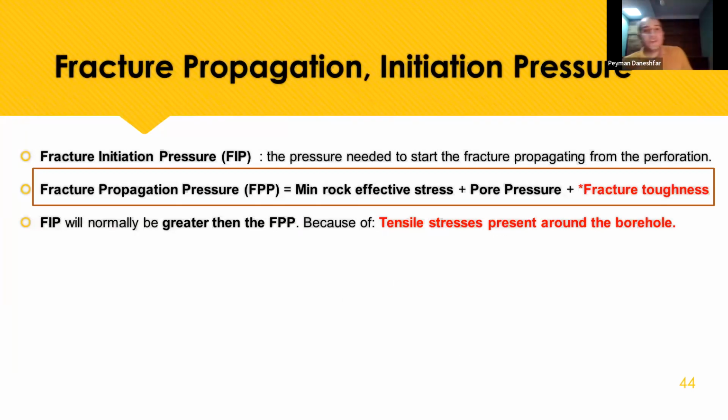What is the fracture initiation pressure? The pressure needed to start the fracture propagation from the perforations. And fracture propagation pressure. What is the fracture propagation pressure? It's the sum of the minimum rock effective stress with the pore pressure and fracture toughness. What is the toughness? I told you before, and I will explain in some next slides.